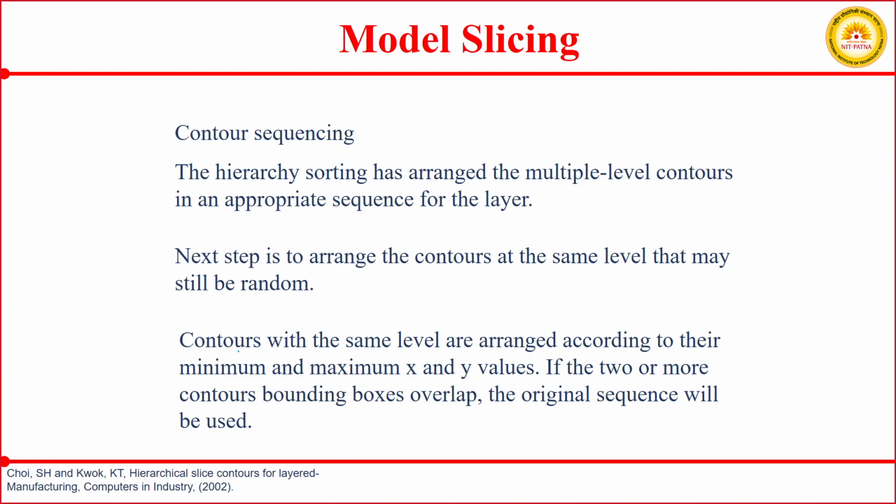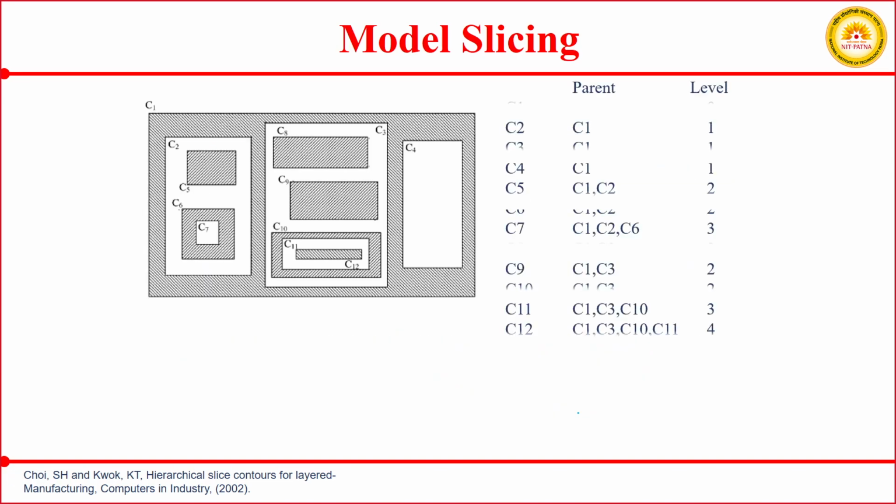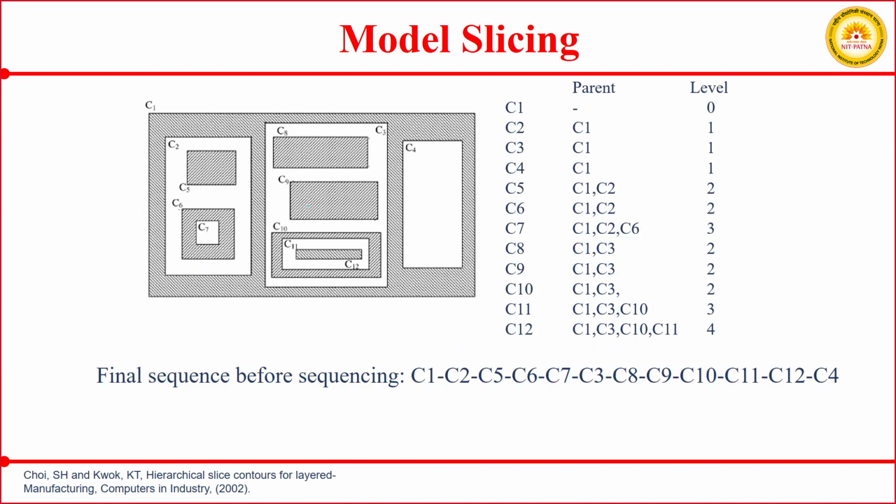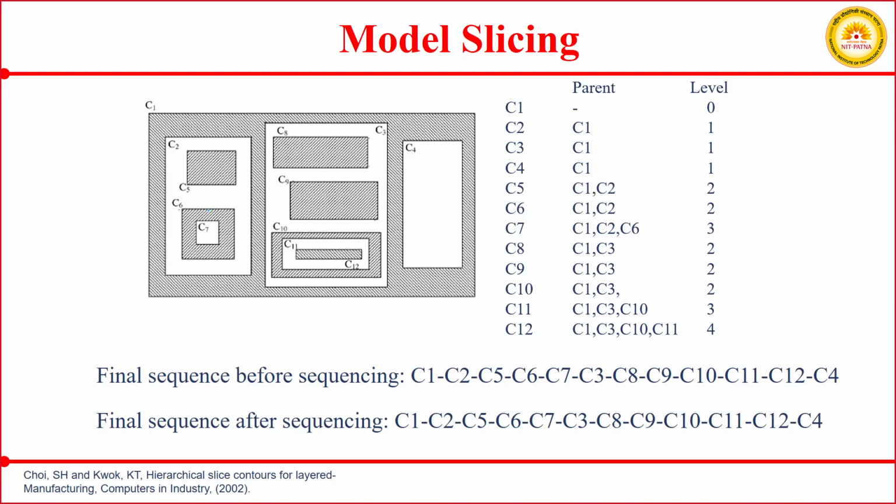The contours with the same level may be arranged according to their minimum and maximum x and y value. If the two or more contour bounding boxes overlap, the original sequence will be used. Okay, so you can also practice different sliced models. You can search a few problems from Google. And for today, I think I will stop here, and we will continue the rest part in the next class on Monday. Okay, if there are any query, we